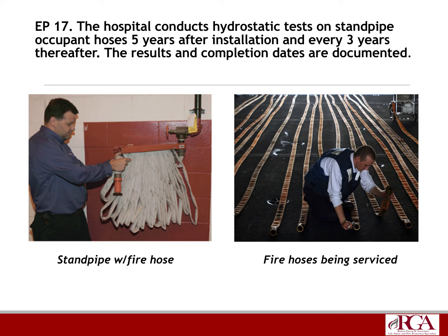Send a letter to your local AHJ and find out if you can remove them. This way you don't have to maintain them, because in essence no one's really going to use them in the event of a fire. So why have them? But if you do have them, you do have to have them hydrostatically tested every 5 years and then every 3 years thereafter. Oftentimes, like the extinguishers, you can just purchase new hoses in lieu of servicing them, because the service is semi-comparable in cost. You don't have to worry about the integrity of them because they're brand new, straight from the factory.